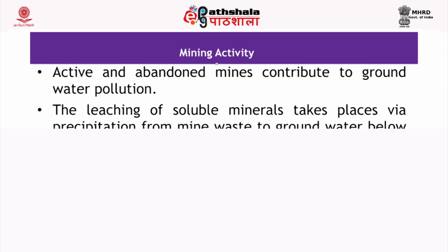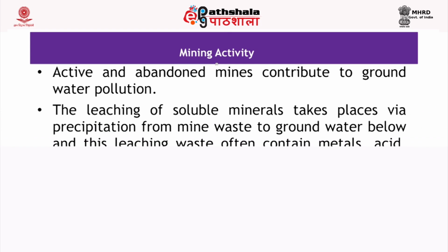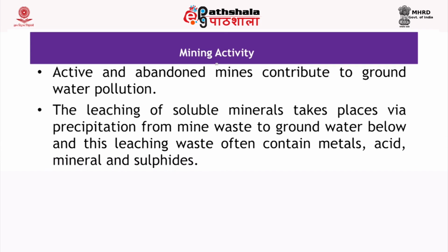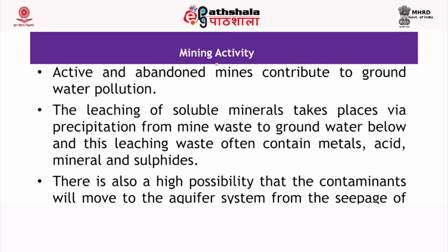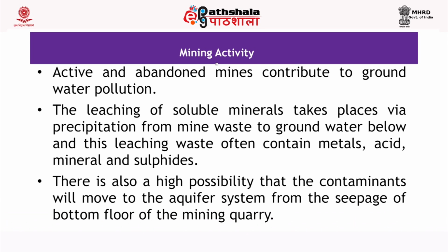The leaching of soluble minerals takes place via precipitation from the mine waste to the groundwater below, and this leaching waste often contains metals, acid, minerals and sulfides. When mixed with the water and percolated to the groundwater, it contaminates. There is also a high possibility that the contaminants will move to the aquifer system from the seepage or bottom floor of the mining quarry.